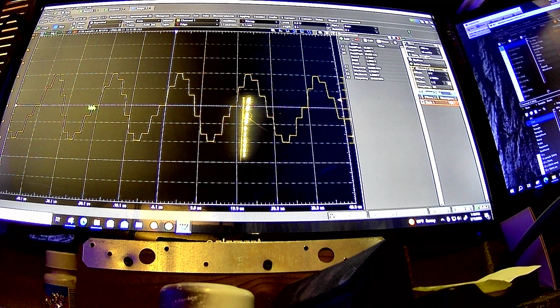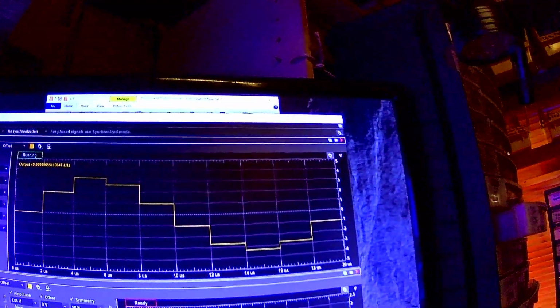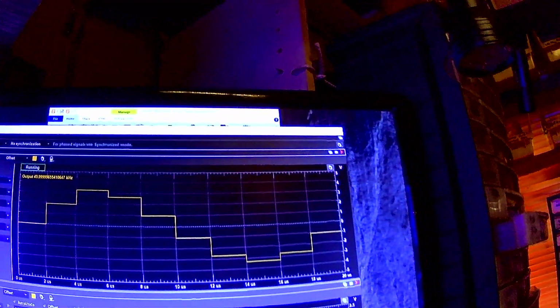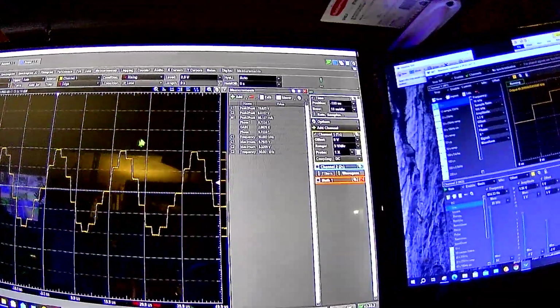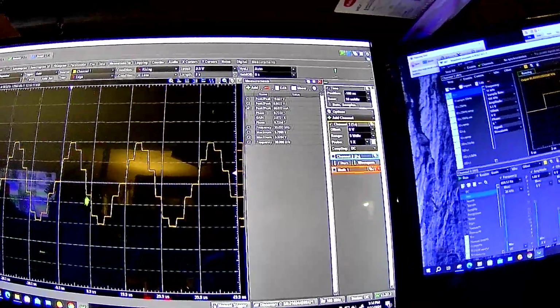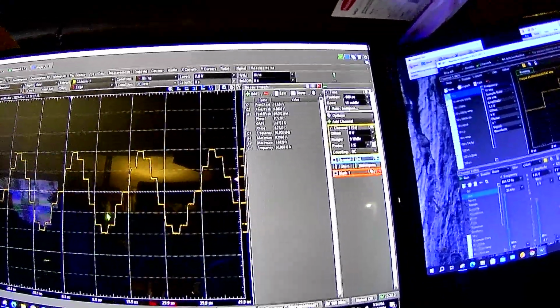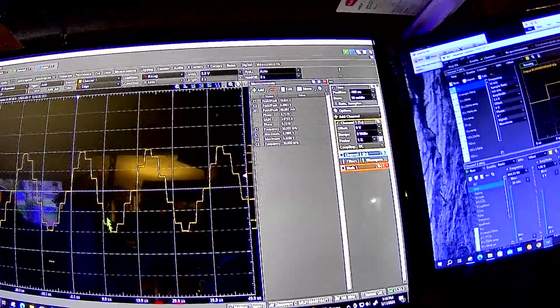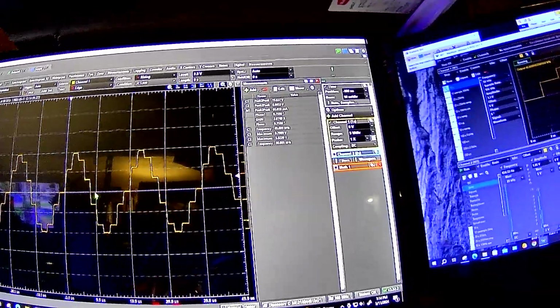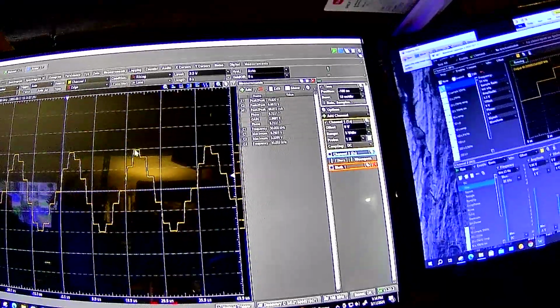and that's because you only got 10 samples per waveform. In fact, you can see over here what it actually looks like. Those are the 10 samples it's trying to generate. If you think about it, you got 5 samples for the positive side of the waveform and 5 samples for the negative side. But that's like 2.5 samples or something from zero to negative and from zero to positive.